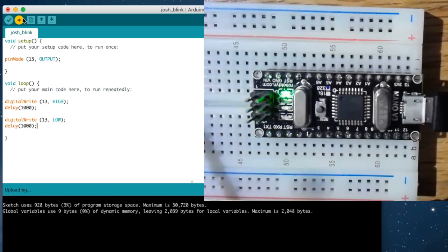Now, if you look at the document camera, you're going to see the LED blinking kind of fast on the Arduino. That's the code uploading. That's actually the serial data transfer happening. Once the serial transfer is done, the microcontroller will reset, and it'll start to execute the code we wrote. So you'll notice now that if you look at that blue LED, it is rhythmically blinking on and off one time per second.